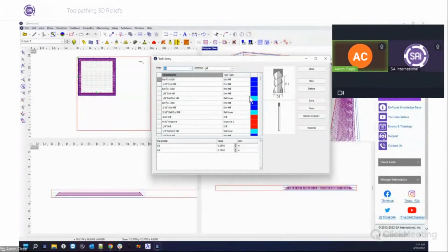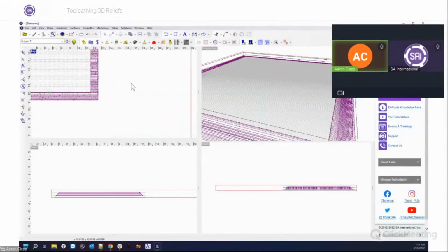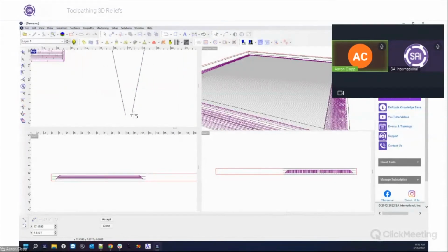One of the things that I will say, though, in regards to your smaller ball end mills, is get one that's tapered. They make tools that are tapered and they're a little bit more resilient. So basically they have this shape to them. They're long and kind of skinny, and then at the bottom, they have a tiny 1/8" bit.